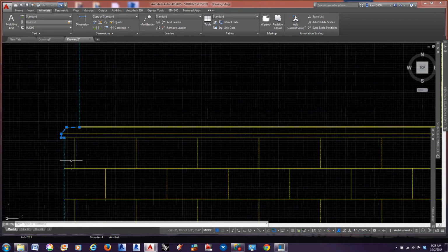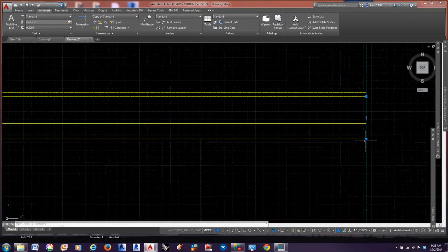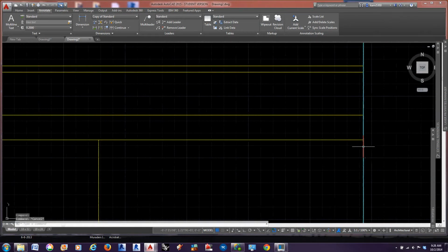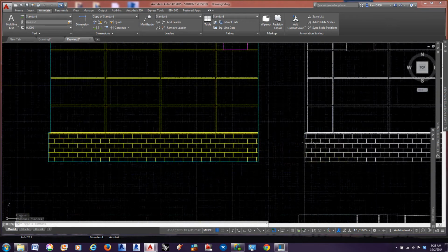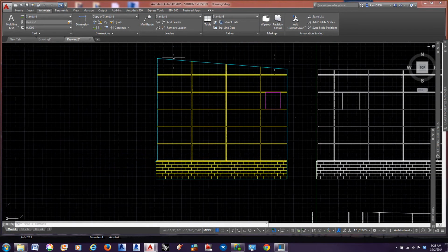And now this whole exterior line is one line, and so the laser cutter will cut that clean completely out without having any issues with breaks in the line. When it sees a new line, it actually stops and starts again. And so if you join your exterior lines together, it'll be one continuous cut all the way around.